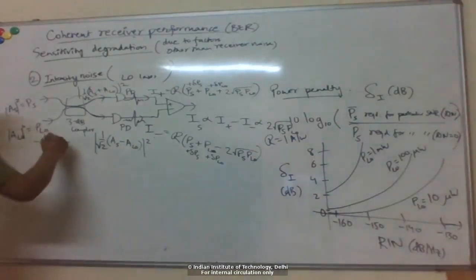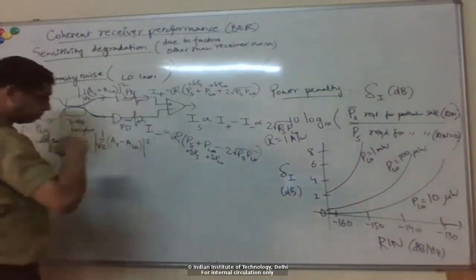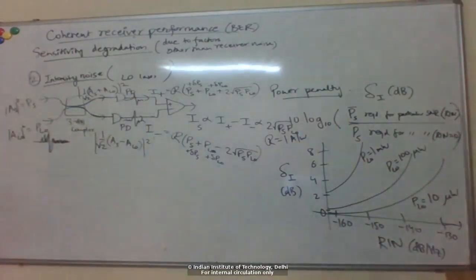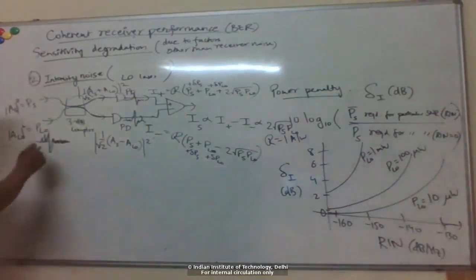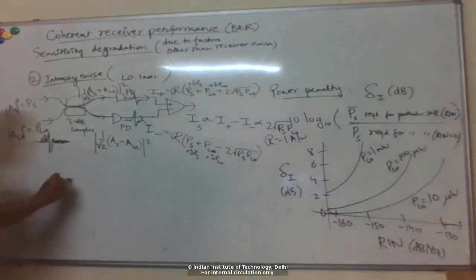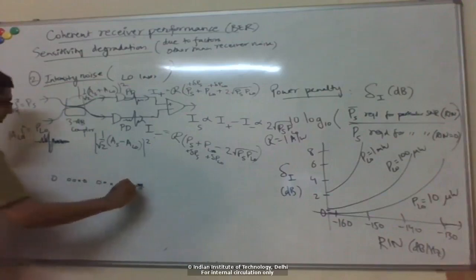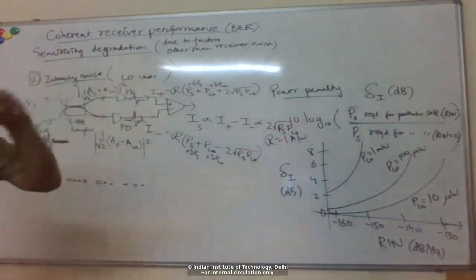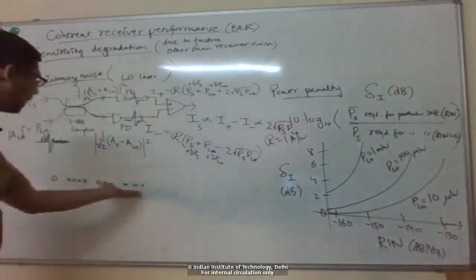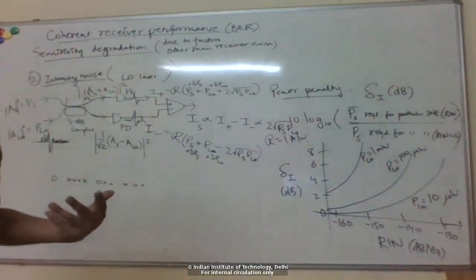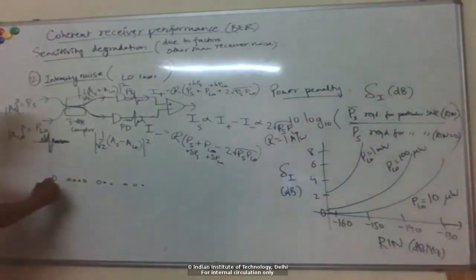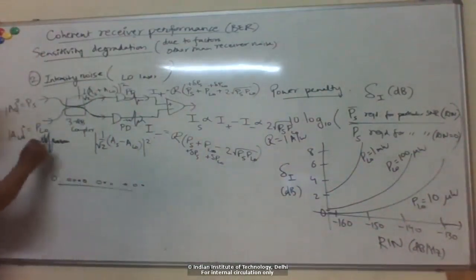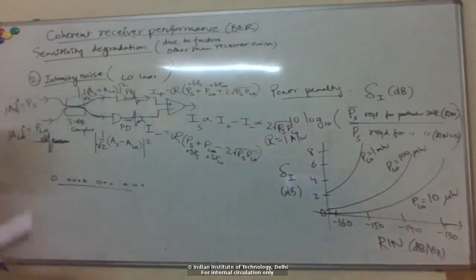So there are a lot of technical noise. All of that will be cancelled out. But then there is some quantum noise, right? Again, we saw that the optical power here is composed of photons which are arriving randomly, right? And this random distribution is some Poissonian distribution, and that is completely random given by laws of quantum mechanics. Okay? So the ultimate shot noise in the optical field won't get cancelled out.